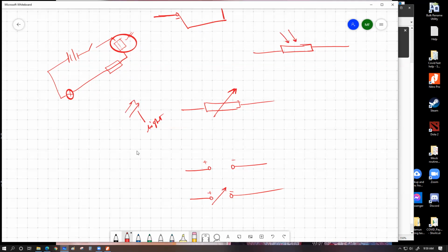Whereas we have LEDs, which are light emitting diodes. They're practically diodes. This is the basic circuit symbol for a diode. A diode is basically an electrical component that can allow the current flow in one direction and not in the reverse direction. So this will allow conventional current in this way perfectly, and this will stop conventional current in this way completely. That's how a diode works. An easier way to remember how a diode looks: it's an arrow with a sort of gate in front. The way I used to remember it is that whenever current is trying to flow in the direction of the arrow, conventional current will be able to go. But if the current is trying to go the other way back, current will be stopped.